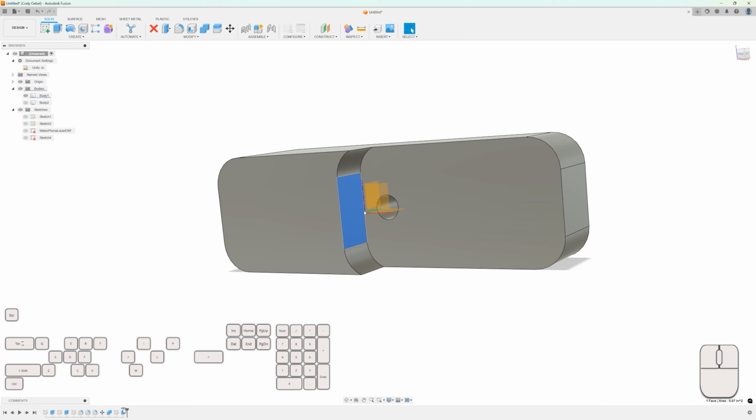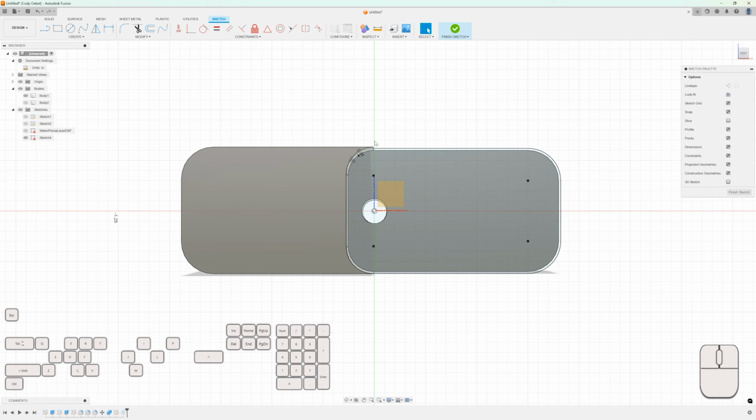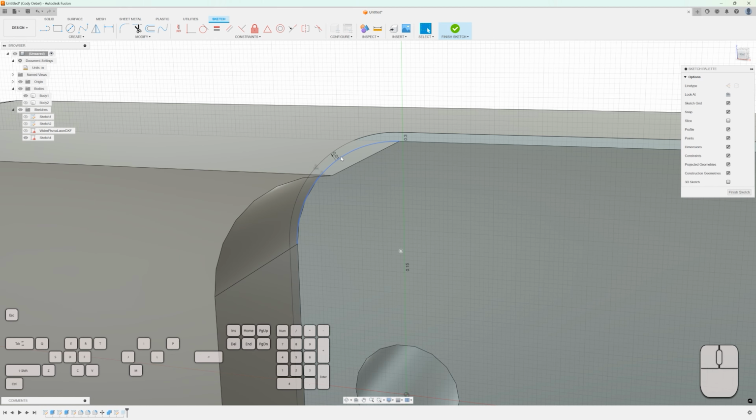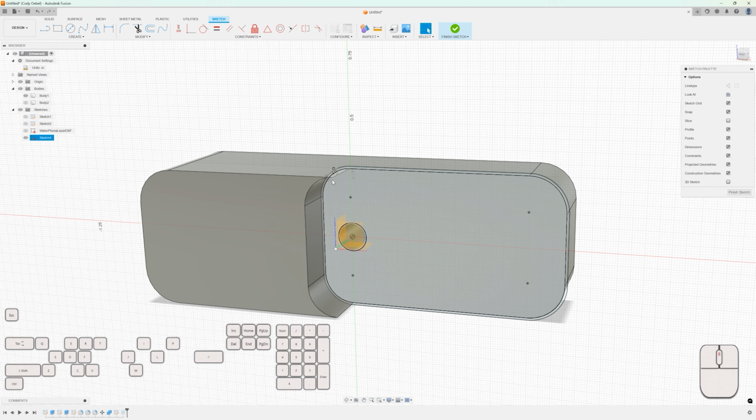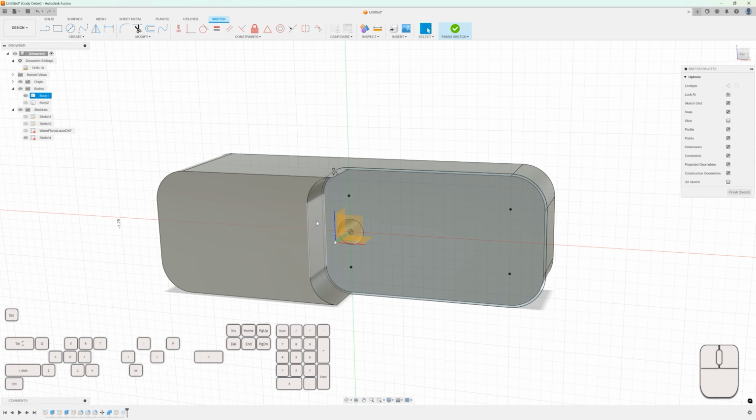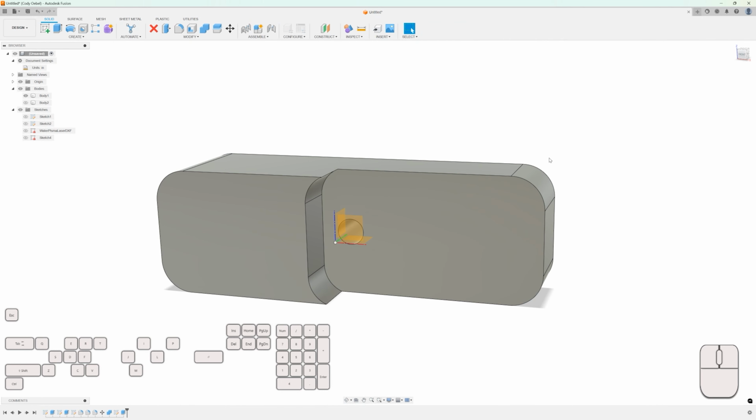Above the feature, remember, we have a sketch and what we've done to the sketch, which is a feature. In this case, it was an extrude cut. So I can also right-click on it, and I can go back to Edit Profile Sketch. So if I click on that, it brings us back to the sketch that was responsible for the feature that cut that face out. So these are huge things to get up and running pretty quick with Fusion 360.